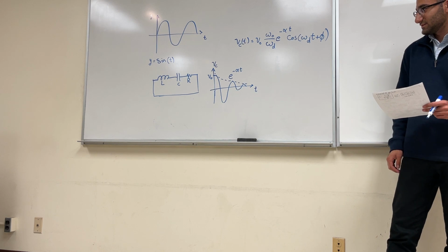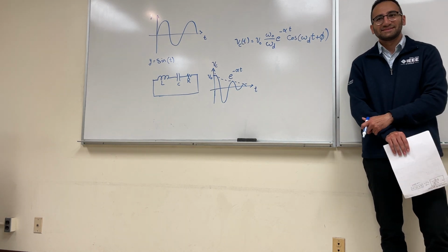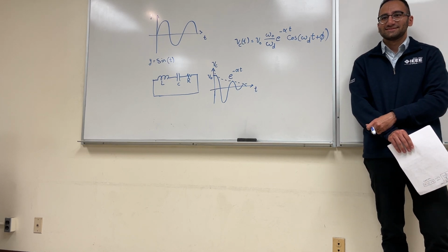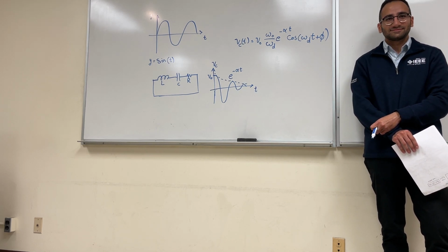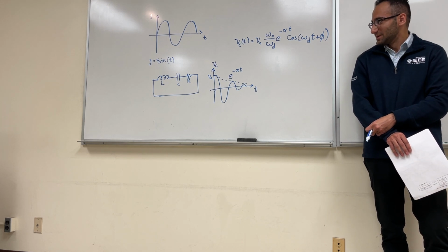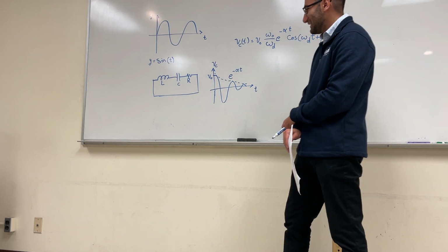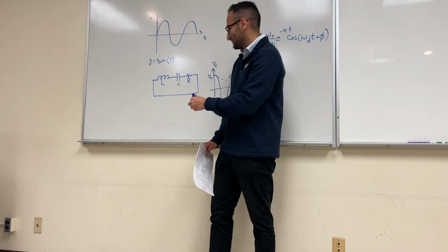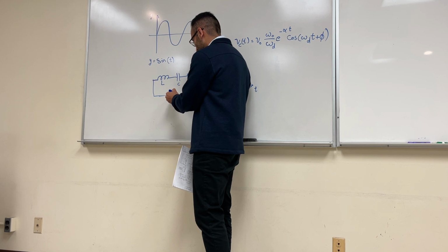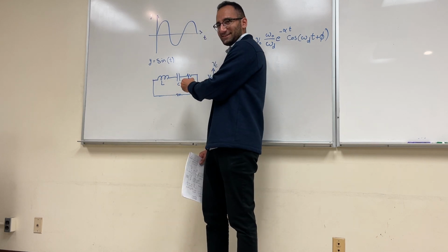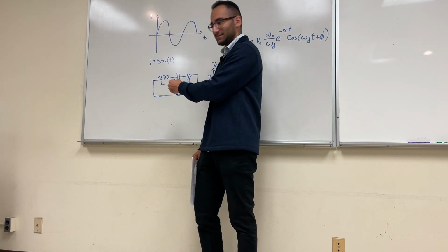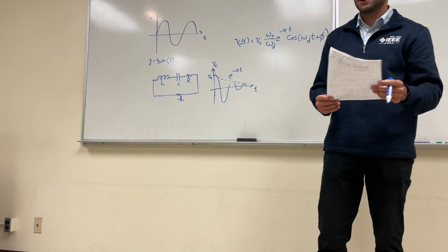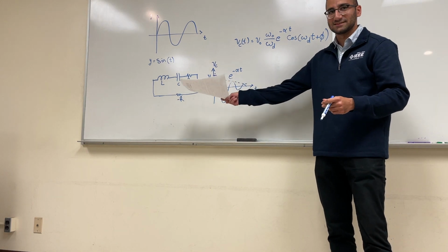So how can we solve this issue? Any ideas? We can get rid of that resistance. So if this is, let's say, some value, 20 ohms, you agree that if I put a negative 20 ohm here, this will cancel this resistance? So negative R, done, problem solved. But the question is, how do you actually generate that negative resistance?